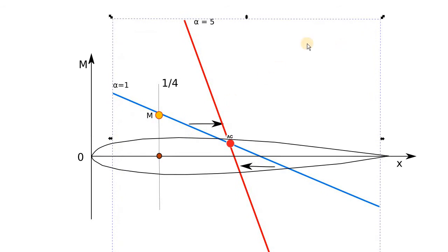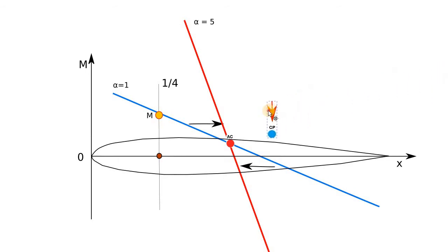So in this case, our moment line is crossing this point where we have the moment value, and this actual point, or this value of moment, gives you a hint on where the center of pressure is located. And we see that for this particular curve and for this position of moment value, we're going to have the center of pressure located here, close to the tail.